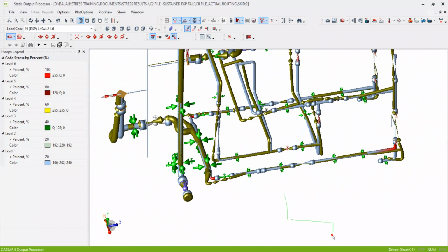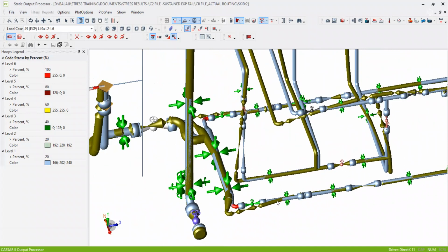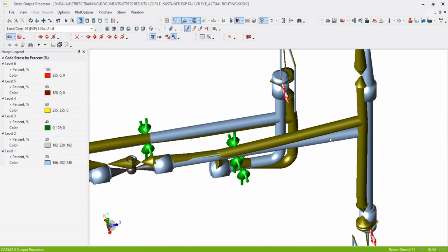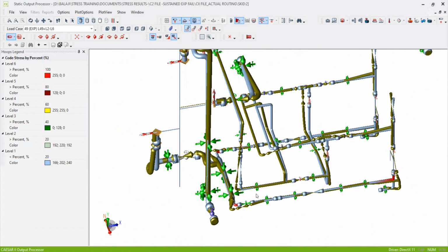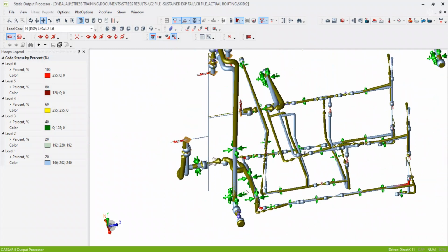So this support is causing failure here also and here also. So we will try to remove the guide support here. If you remove the guide support, definitely it will pass, I think. We'll remove the guide support first here, and here also. Then this failure will reduce.